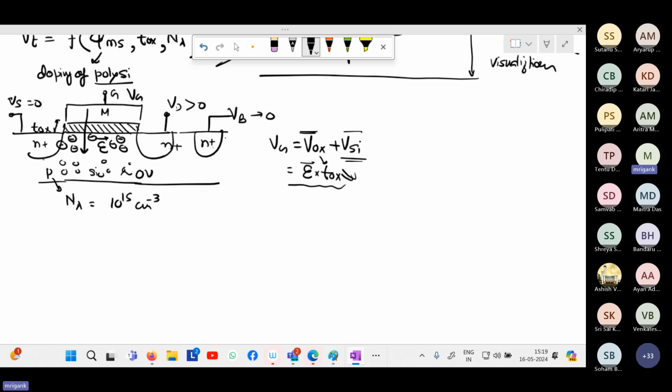In simple way, this is the mechanism. That's why we need a positive electric field. That's why for NMOS, we need to apply a positive gate potential, which will conditionally create the channel by pulling the electrons close to the surface. And then there is a continuous channel formed between source and drain, and the current can flow between source and drain. If you remove that positive potential, then that channel is gone, and in between the source and drain, you have a p-type substrate, which is not going to allow the current to flow. Is that clear, all of you?